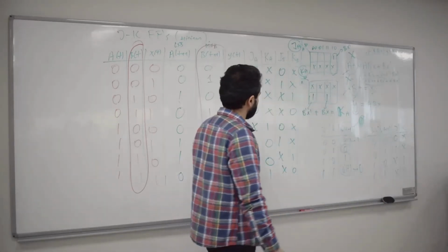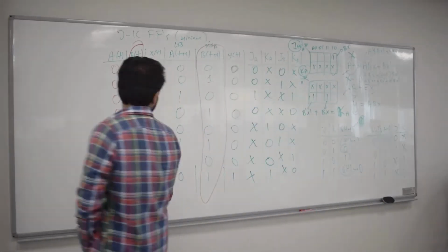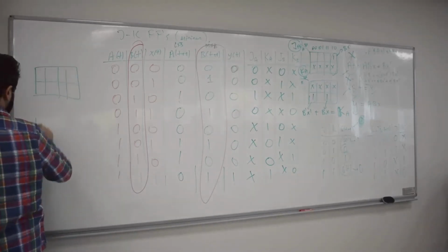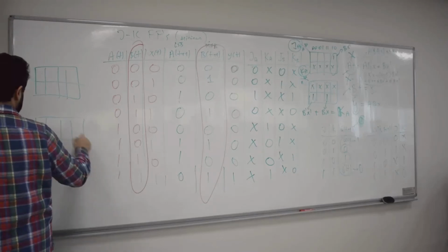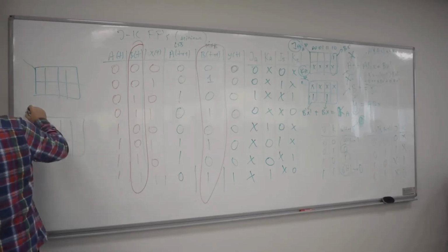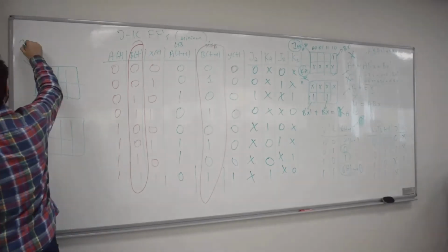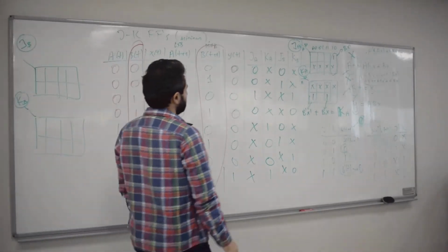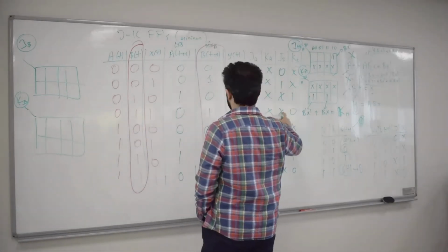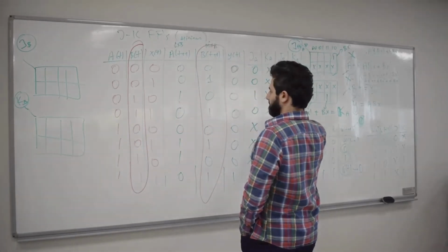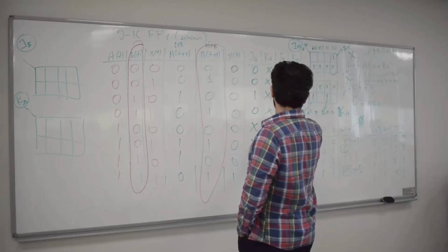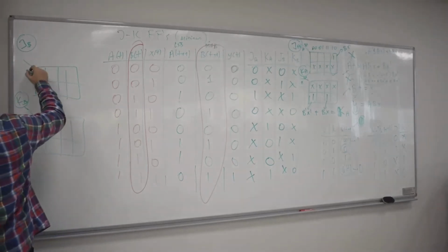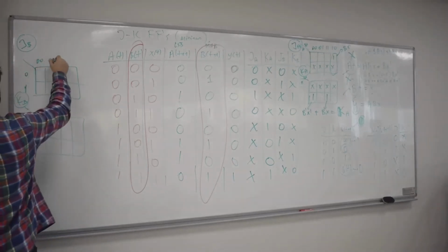All right. I'm going to draw the other 2 Karnaugh maps here, for JB and KB. For JB, I have don't cares for B is 1. So this is 0, 1, 0, 0, 0, 1, 1, 1, 1, 0.